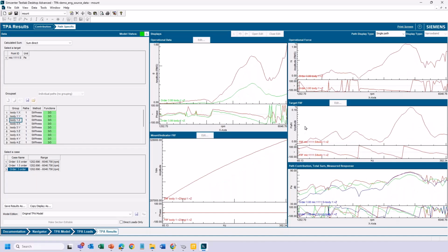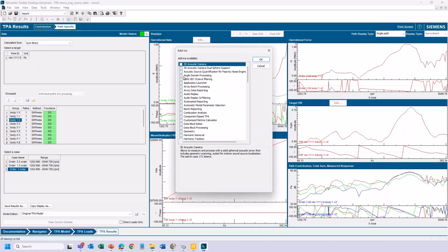And would you say it's the FRF, the structure, or the force, the motor or whatever, that's creating the problem? Possibly the force, it looks like. The peak is up in the force. The peak's up in the force, but I think it's a perfect storm. We also have a peak in the FRF. The force and the structure are combining to cause the problem. If you're at a company, you get to blame both the structures people and the source side people.